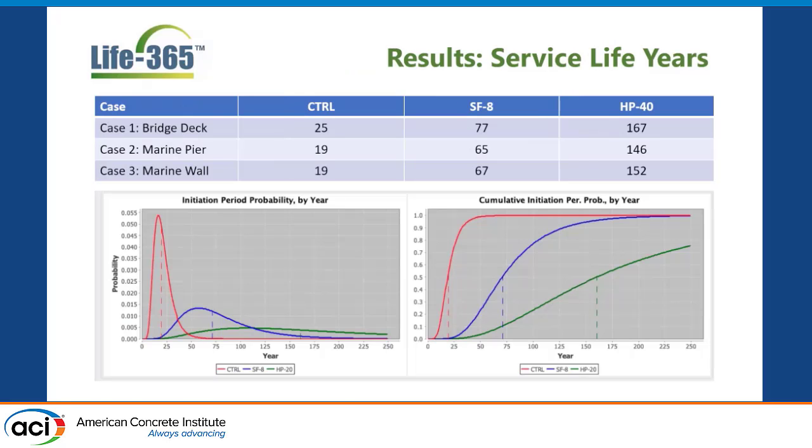And then these are the service life results that I get out of that. For the control, it's around 20, 25 years. For the silica fume replacement, it's around 65, 75, 80 years. And for HP40, 167, it's around 150 years. So, big differences. The best first outcome of Life-365 is that these guys don't overlap each other.